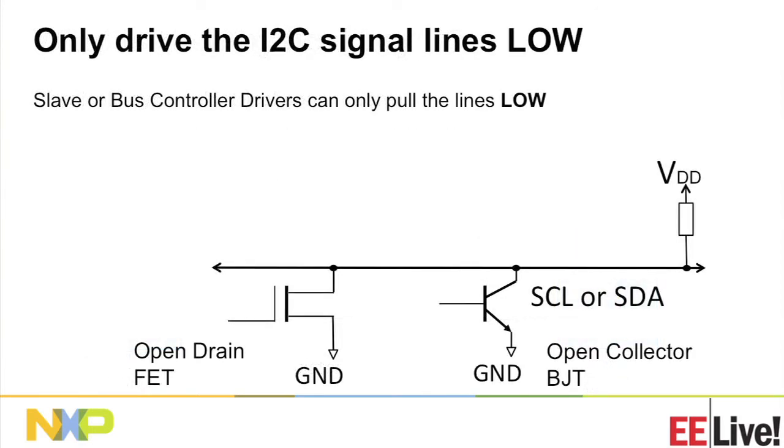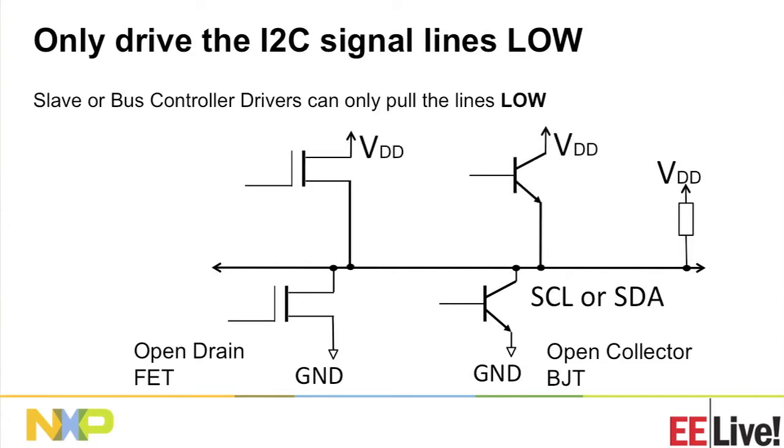One of the things that's characteristic about the I2C bus is the devices pull the signal lines towards ground. At no time should you pull it high. So this diagram is not legal. We'll cross those out. In your mind, you should imagine a connection that is pulled to a positive supply with one resistor, and multiple places along that line you can pull it to ground with switches. Typically today they're FETs. Older technology, bipolar devices, are still valid, and they may use bipolar transistors.